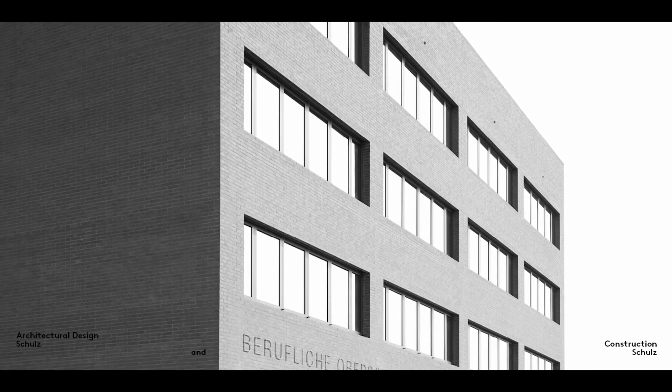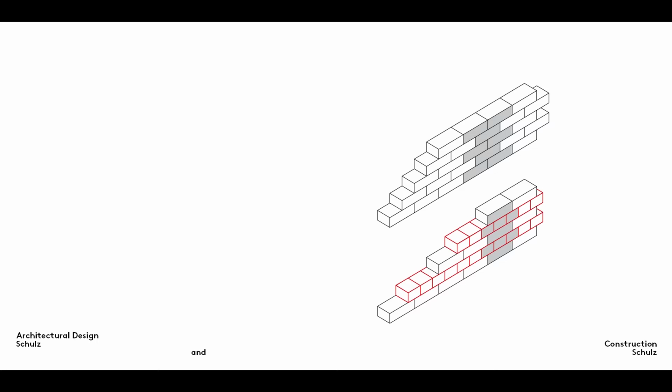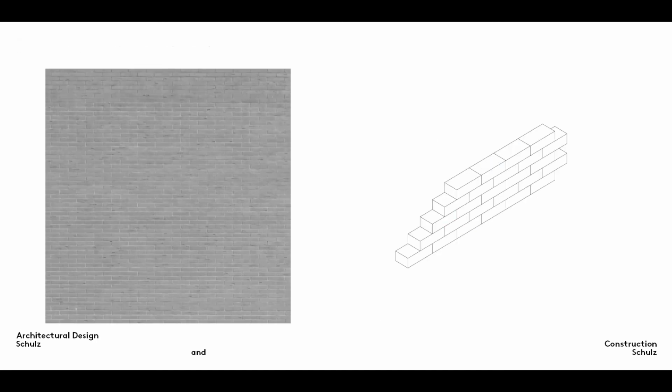Ground plan dimensions are based on half brick lengths because the bricks are laid in patterns or bonds, generally a stretcher bond, in which the bricks are offset by half a brick. The half brick thickness of the facing skin limits the bonds that can be used, since bricks cannot be laid at right angles to the direction of the wall. Half bricks do exist, but they increase the cost of the wall and are better suited to the construction of solid rather than double skin walls.